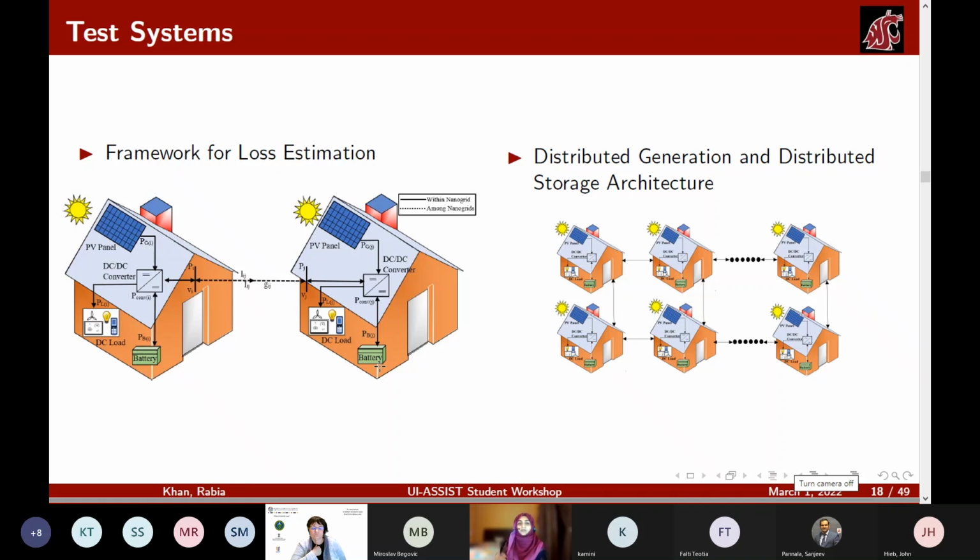I know batteries are expensive. And we have also assumed that the loads in remote rural areas are not very high. We can design based on what the load requirements are. So even if PV is not there, the battery will be there, and the converter has to optimize whichever is connected, or even both, or even when it is charging.